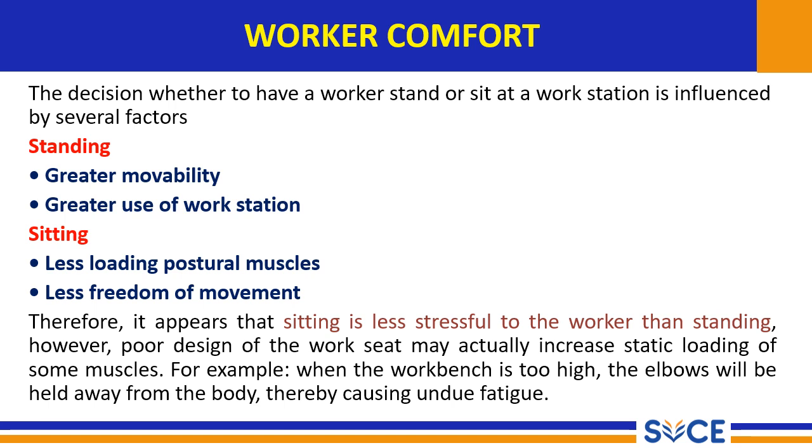When they sit, they have less freedom of movement, there is some sort of constraint, but they have less loading of postural muscle. Therefore, it appears that sitting is less stressful to the worker than standing. However, poor design of work may actually increase the static loading of some muscles. For example, when a workbench is too wide, the elbows will be held away from the body, thereby causing undue fatigue.